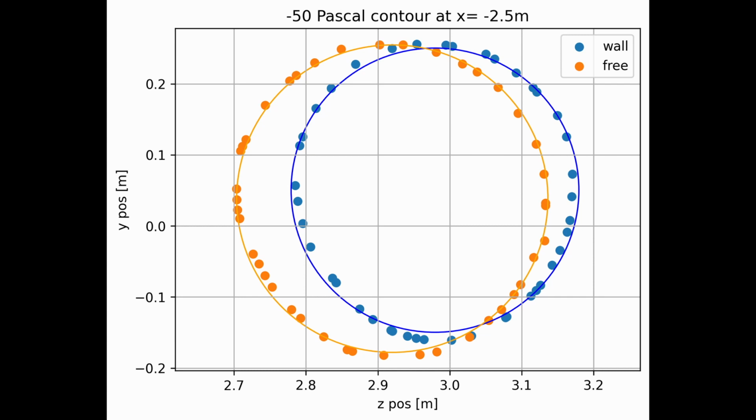Looking at the rings, first of all, we can see that our wall case is indeed curved slightly outwards. Remember that now we are basically looking at the front of the airfoil compared to the previous pictures where we were looking at the airfoil from the back. So as we move right, we curve away from the airfoil, and we can also see that the height of the vortex core is increased. This makes sense since we have the high pressure area and the ground as an obstacle.